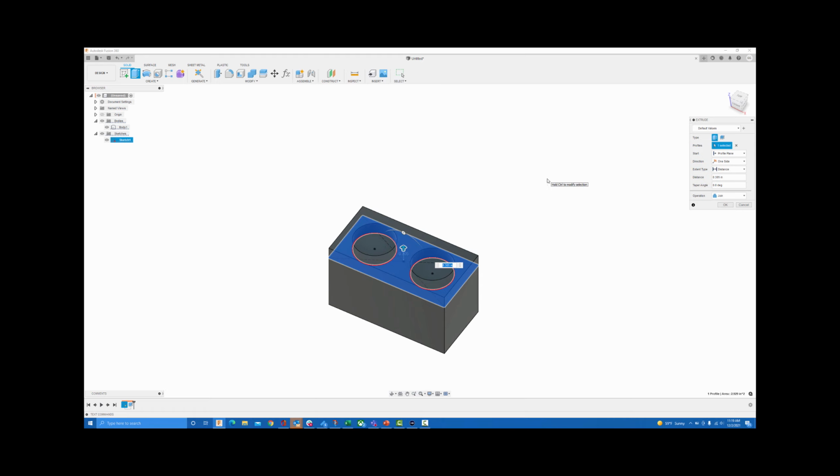There are differences between a component and a body, where these are going to be 2 different things that I machine separately, probably have 2 different part numbers. I really should do them as components. If you do them as bodies, you can turn them into components later, but probably a little bit deeper conversation than here. So for now, I'm just going to say we're going to make 2 bodies instead of 2 components, but in hindsight, I probably would have made each of these.